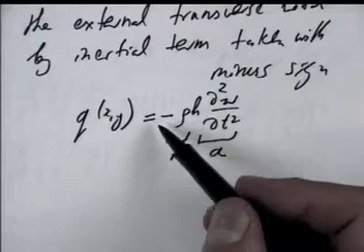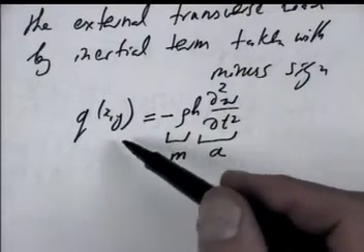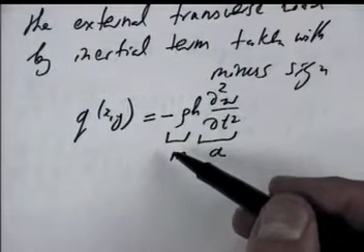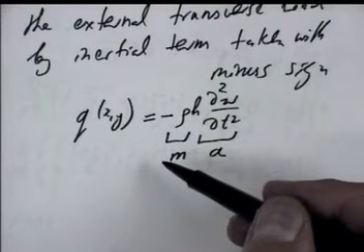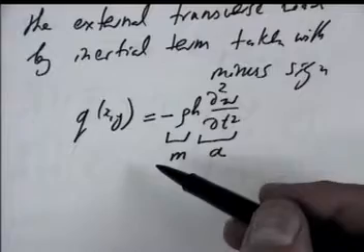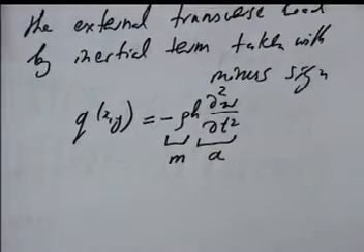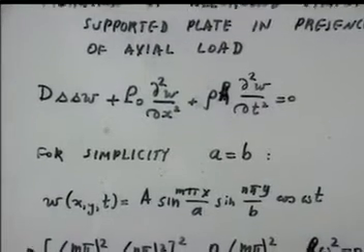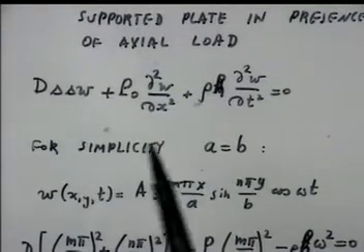So he says just instead of this load f, you put minus, because that is how vibrations will be conducted. Once we take this into account, we get this equation. I transfer this minus rho h d2w over dt squared to the left-hand side, and I get this expression.